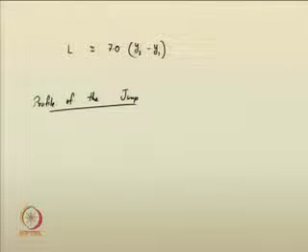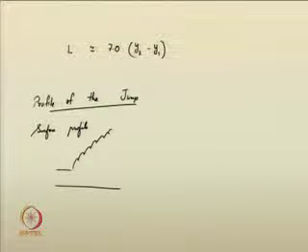The next portion which we have to cover is now the profile of the jump. We are mainly talking about the surface profile. This entire portion is called the surface profile, how the jump is occurring from this steep slope, from this supercritical to this subcritical flow. In that case, what is the water profile? Due to this change in profile, it is called rapidly varied flow, as we have studied earlier.